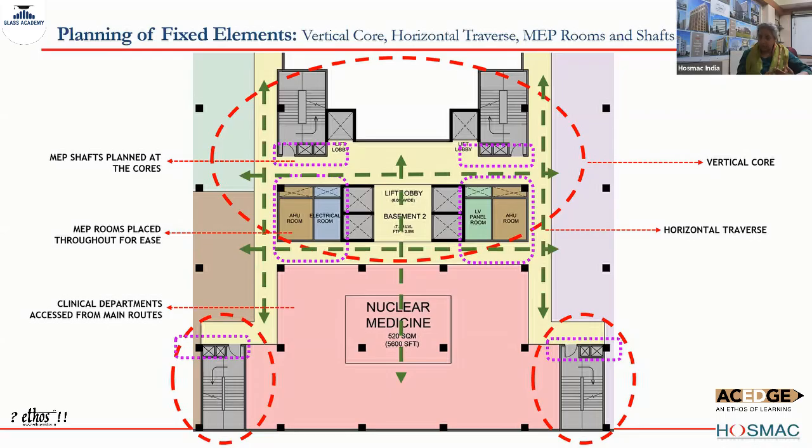It is always a good practice to put these shafts for electrical services, plumbing services, HVAC services next to cores, vertical cores. And that is part of concept design. Architects really miss that. We shouldn't. We are conscious healthcare planners. We should get these. So in this plan, if you see, there's an electrical room next to a vertical core. So let's do that always.